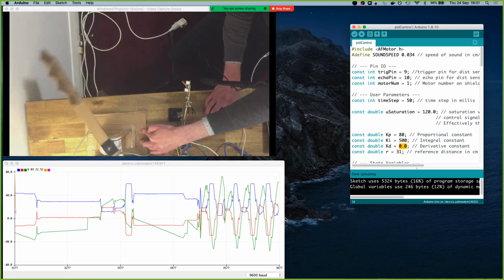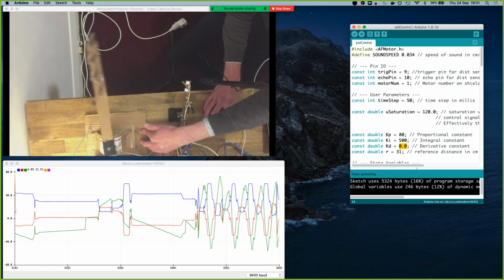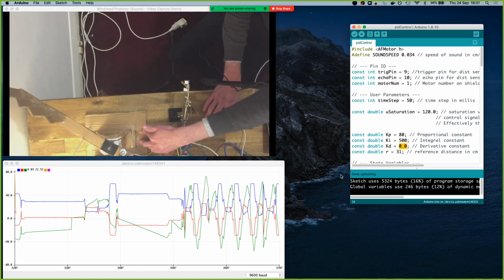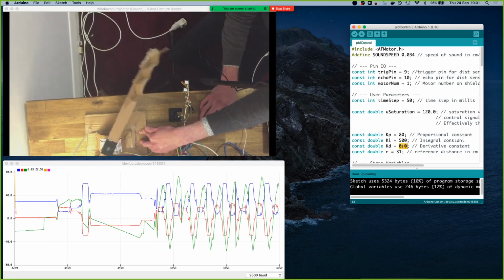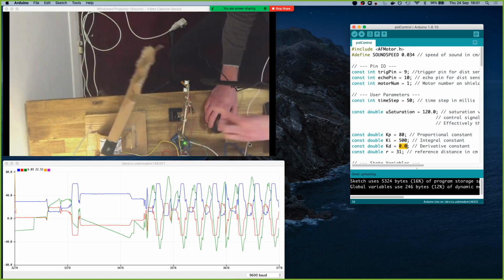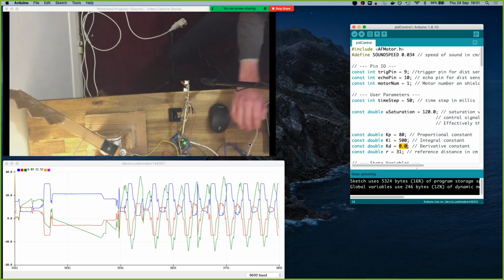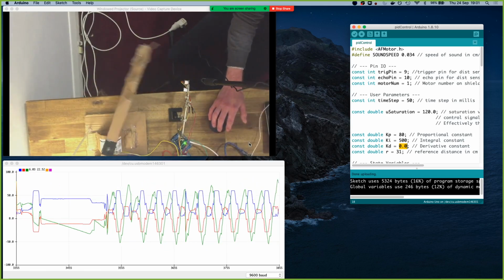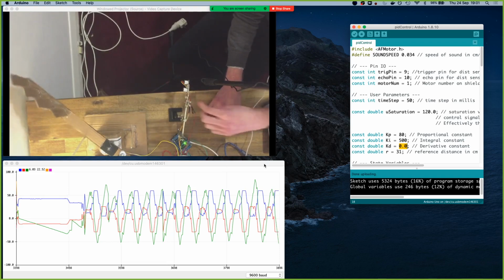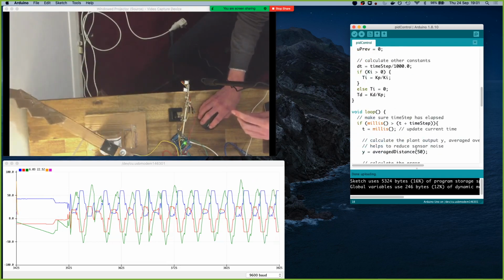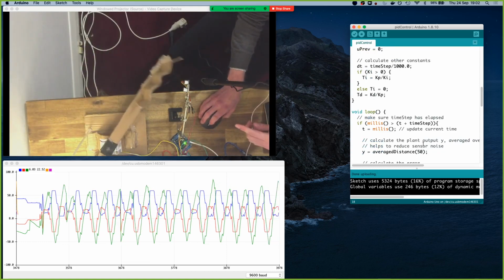I had a lot of trouble. This is a geared motor, because the original motor was quicker, but it didn't have enough torque. So we can see we've got some sort of oscillations here. This sensor is not ideal because it's an ultrasonic sensor working off the echo. Any movement is going to bring spurious readings from the Doppler effect. It also takes time for the bounces, and we're doing 50 averages of individual readings. So it's not ideal.